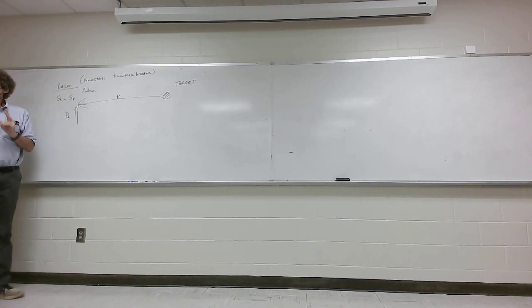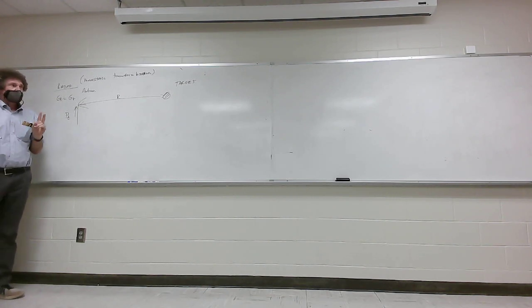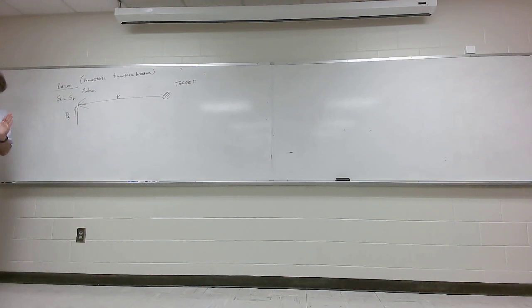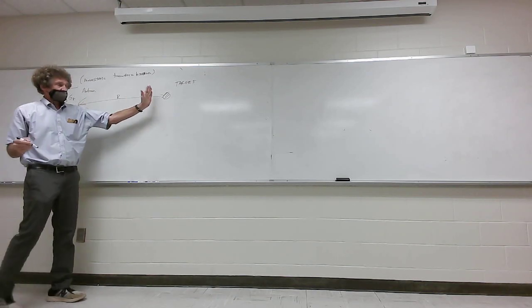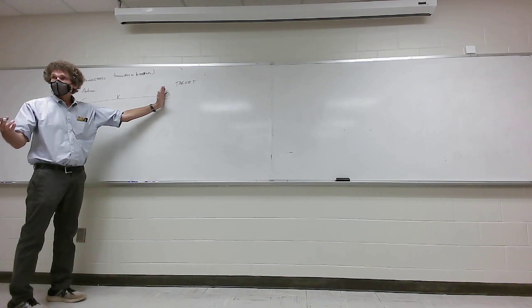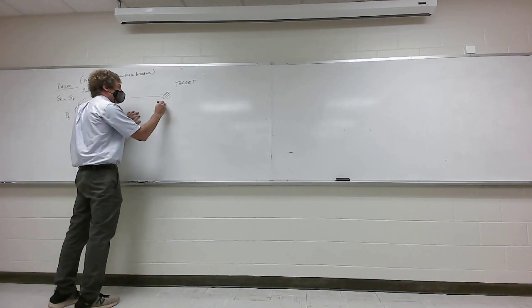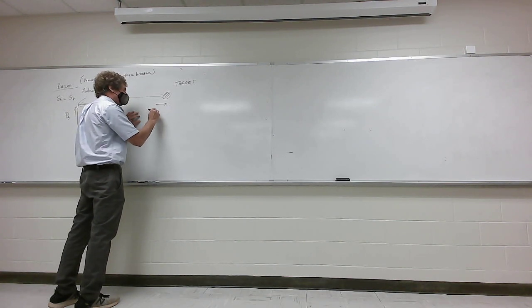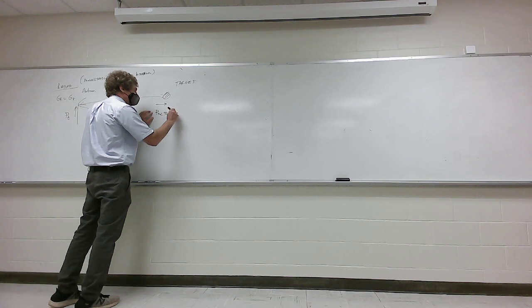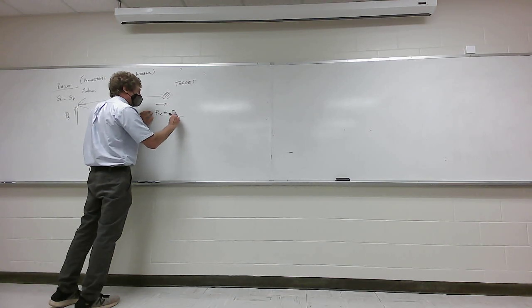So the first thing we do is find the power density incident on the target from this antenna. And this is the way I tell people to always do this. We're after the power density right here. Y'all follow me? That's so critical. If you can't get power density on a target, you can't get a reflection. So here, I just call that P incident here on the target. That would be the transmitted power over 4 pi r squared.